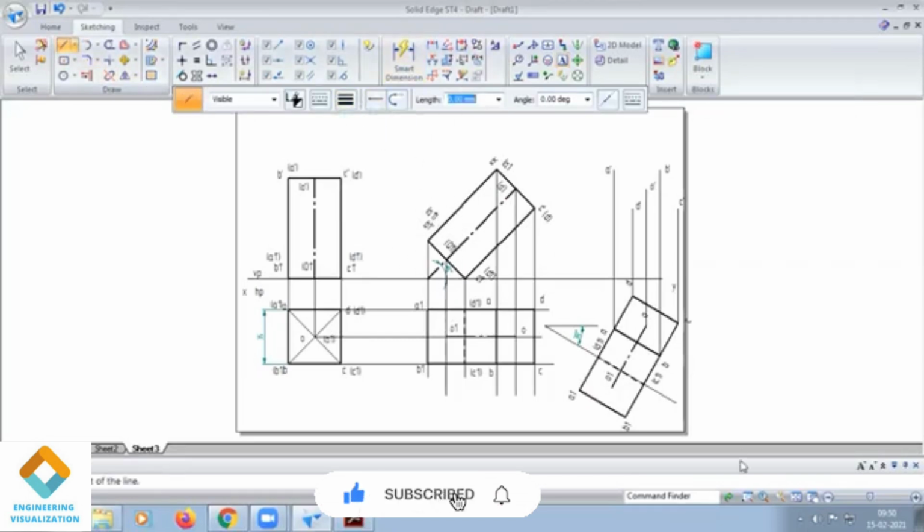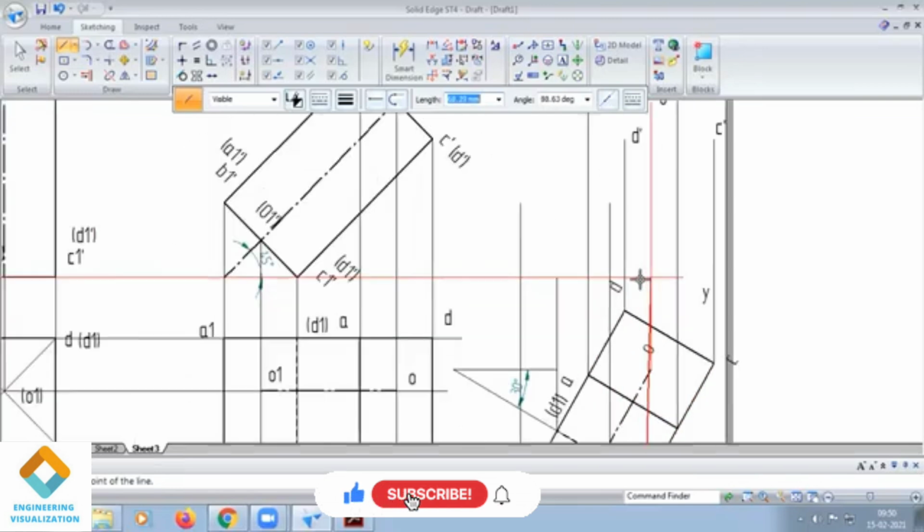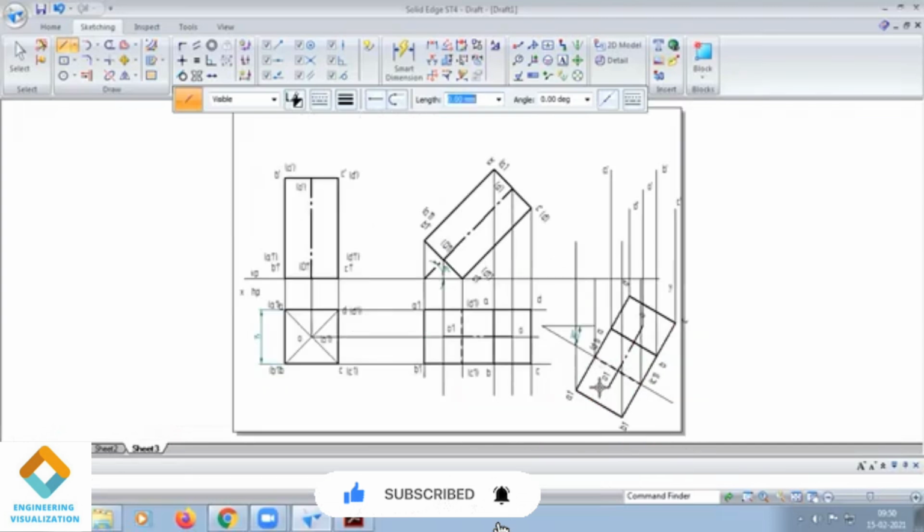So now similarly we will write for the bottom face. Okay, so this bottom face and this bottom face we will write. First one it is A1. So A1 it is extended till here, A1 dash. So these 2 points are merging here. Similarly B1, so here exactly we get it. Next with D1, D1 it is on the XY line. And similarly we have C1, C1 also here till XY. Okay, now finally we have O1 till here.